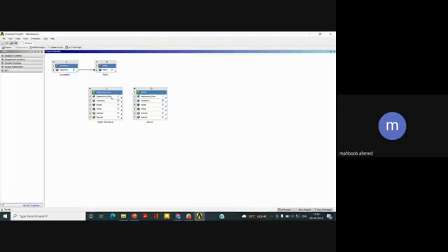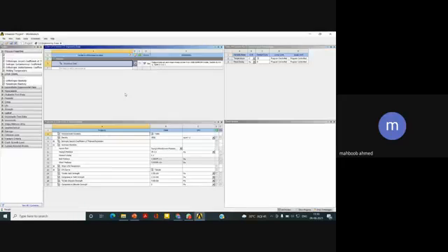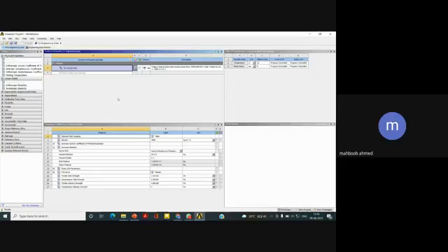If you want to add some other materials, you just double click on this and your material section will open up. You can see it is showing structural steel by default. If you do not want structural steel, just click here and it will suppress it, so it will not be considered in your design.